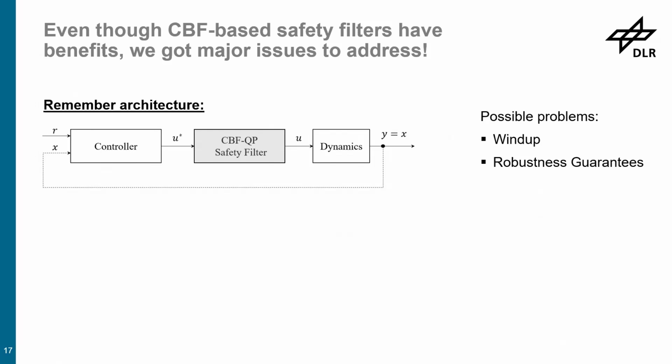Another problem is that you will have issues with your robustness guarantees. I think we talked about it also in the meetings before. Normally, especially in aerospace, when you design a controller, you always have to make sure that you have certain phase margins, certain gain margins, right? Otherwise, you are not able to certify your controller.